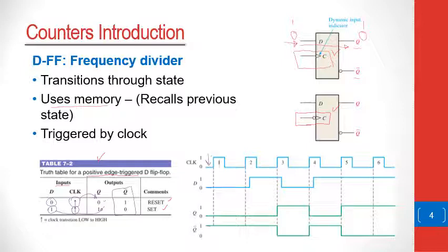Now on the positive edge of the clock, whatever is in the D will simply propagate to the Q. So if there was a 0 in the D, the 0 will come to the Q. Because this was 0 and this was 0, the 0 will simply go into the flip-flop and show up as Q. So nothing will occur. There will be no change in the Q output.